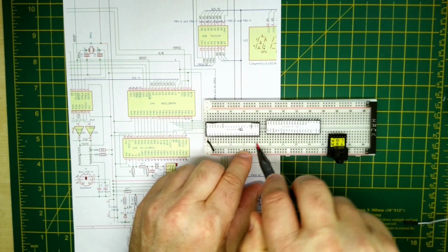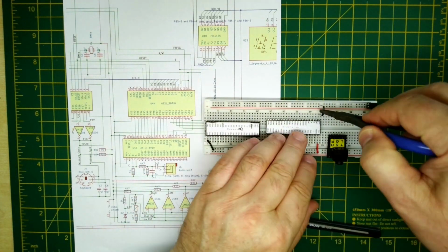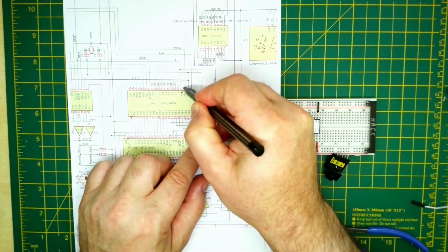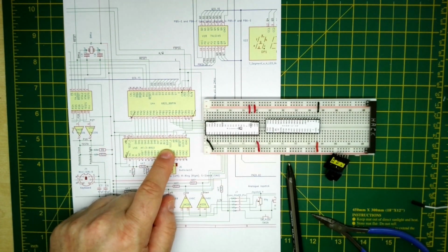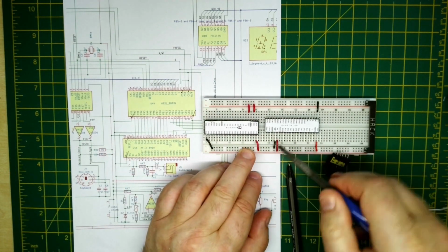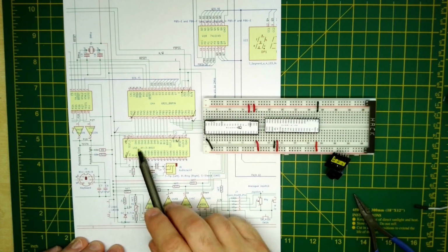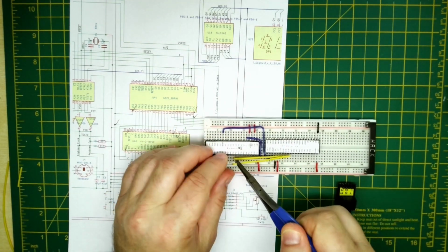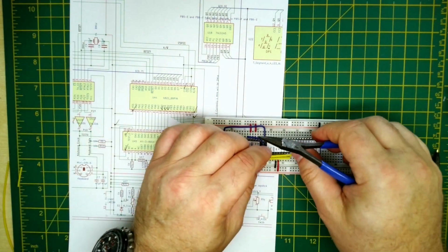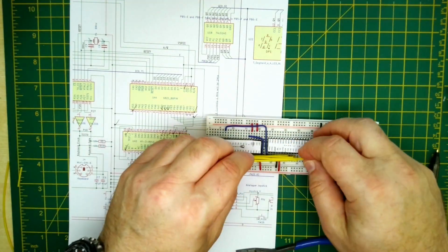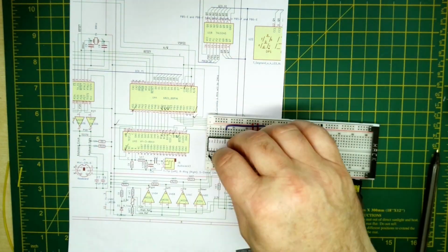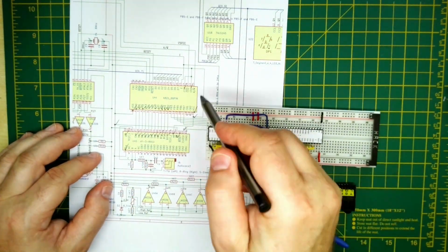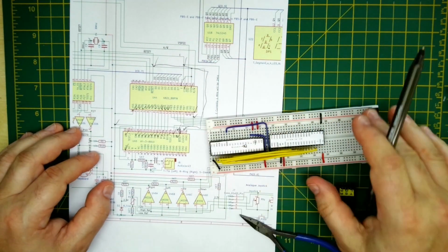Okay, so just wire up the power lines for the 2 chips, check those off the diagram. Now we're going to wire in the pins that need to be tied to +5 volts or to ground, things like chip select signals. Check those off. Now we're going to wire in the output for port A and port B over to the sound generator chip. I did forget to record the video for the reset and the E signals, those blue wires coming through there. We've also missed out the reset signal on the schematic diagram, so we're just going to need to add that back in once we've finished the video.